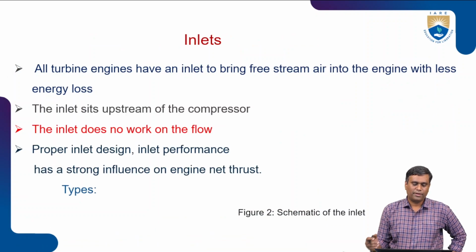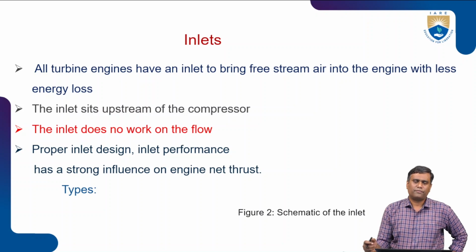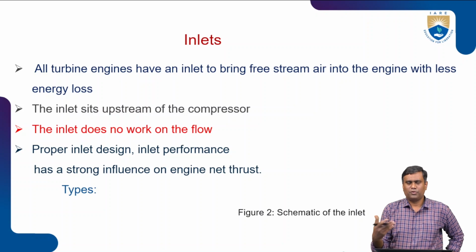So the primary function of the inlet is to capture free stream air and transfer it to the immediate component of the engine, that is the compressor. Right. So the function of the inlet is to capture huge amounts of free stream air and transfer it uniformly to the compressor with fewer losses.